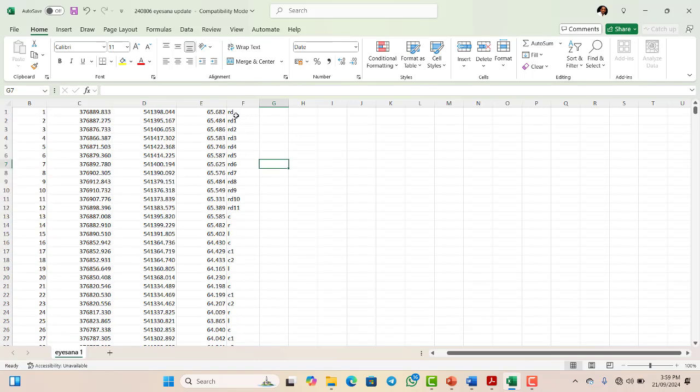Now these are descriptions that define the survey or the features along the road alignment. Like what this RD simply means is road. There is an adjoining road. So the surveyor used this to describe an adjoining road, and the C here represents center line. There are some surveyors that use CL, but this surveyor decided to use C to represent the center line.